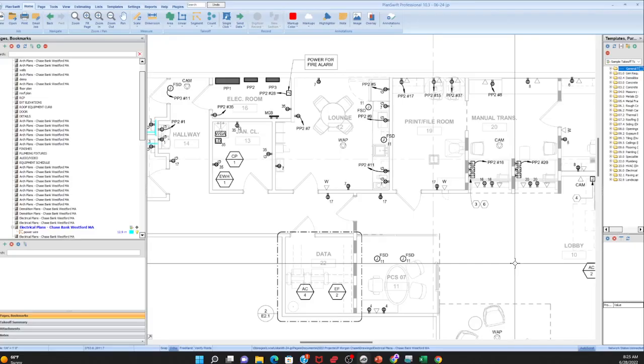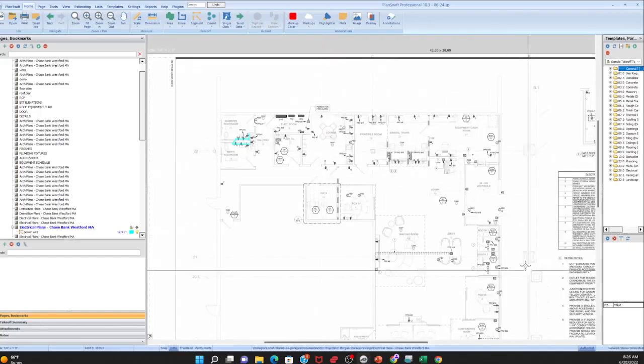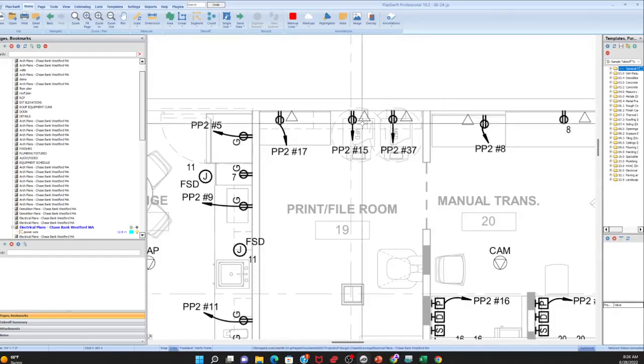Okay? And so sometimes things are hardwired, which means, like in an apartment complex, they'll hardwire the refrigerator, which means it's not connected to a plug, but it's connected through whatever wire configuration directly to the panel. That's hardwired. So, when you're doing the takeoff for the power plan, you want to make sure you're doing all of your things that look alike.